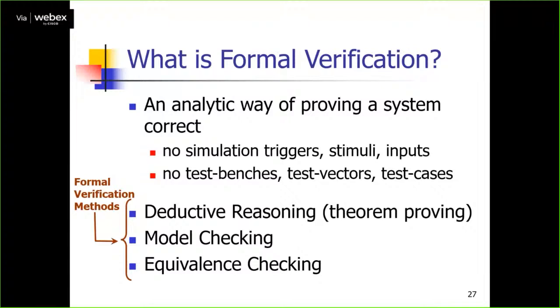Here there are no test vectors to be inputted. Input test vectors will not be there. You are not creating test vectors. You are not doing any test cases either. You are just doing deductive reasoning. That is theorem proving. You are going with a model to model mapping, an equivalency from one model to another model to be checked.